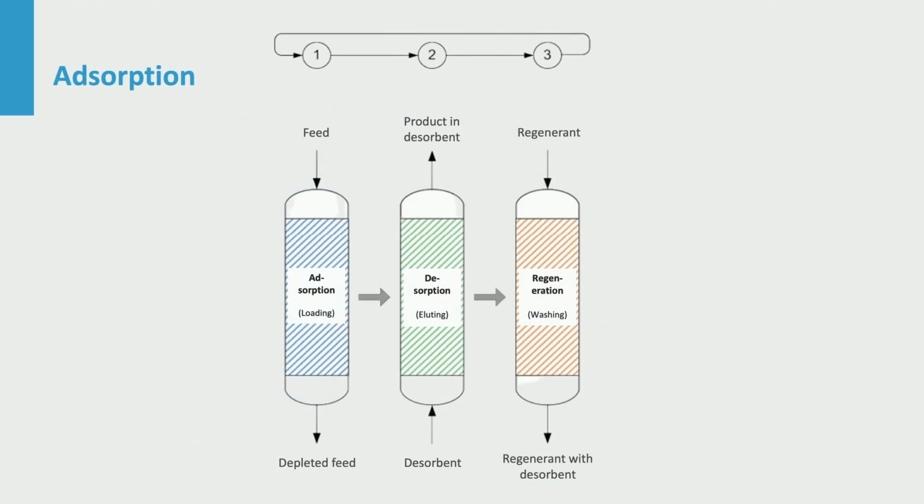A product or side product in a feed may be removed to a sorbent phase instead of to an extractant phase. Selective sorbents may be found, leading you to a useful separation factor. Sorbent doesn't easily flow and is preferably packed in a column where it is used batch-wise. To approach continuous and even countercurrent behavior, one can use cyclic arrangement of alternating columns. Those are not elaborated here.